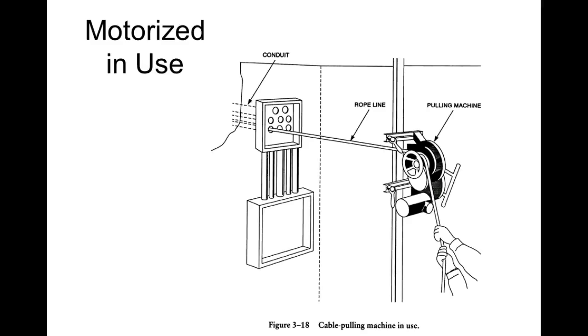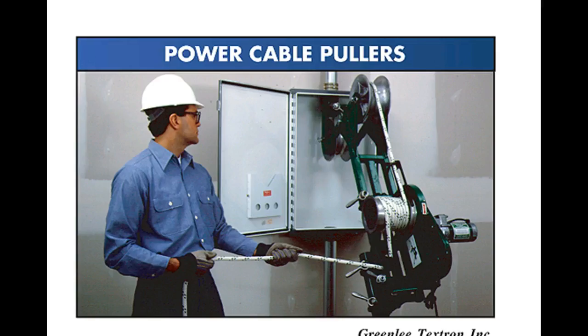This is a real good picture right here. So what we do on the capstan is it's laced over there, and if you pull tight on it and then you pull, if you let it off, then it'll stop pulling. This guy here is holding tension on the cable all the time. This is the pulling rope. This unit has the pulling sheave on it. Can y'all see the pulling sheave? Because what the pulling sheave does is it changes the direction of the pull.